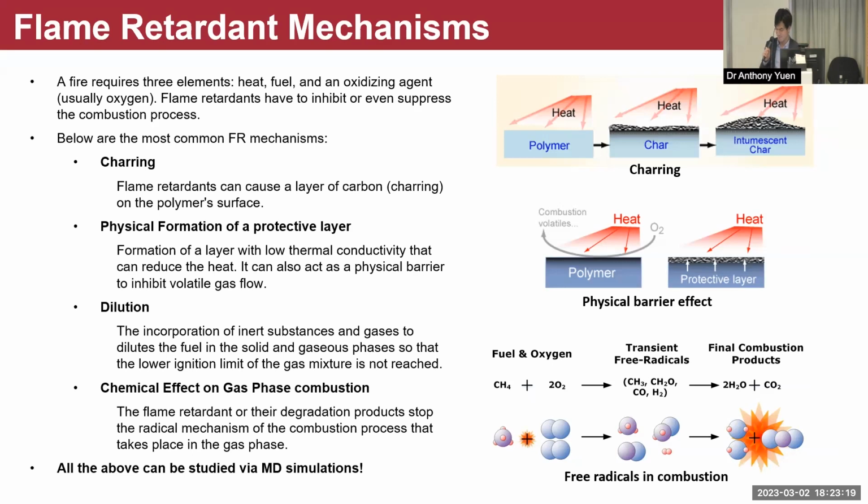But we did some other studies involving intumescent char, which will also cause the polymer material to char and even expand. And it gives a bit better protection to the material. We call that a synergistic effect. But anyway, the physical protection could be due to char or could be due to the formation of a thin layer that is not heat penetrative.